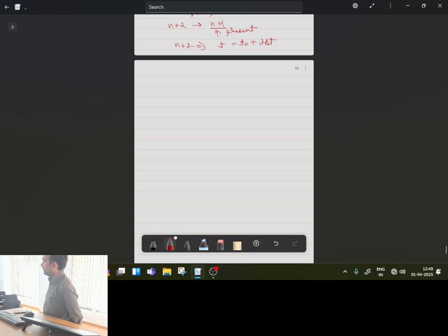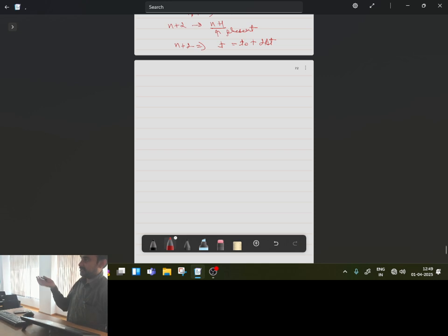As I have already told you, we have the continuity equation, 3 momentum equations in each direction and 1 energy equation. But to understand the effect of flow, before going into the exact equations, we can start with one simple generic equation which is called the scalar transport equation. What is the meaning of this?